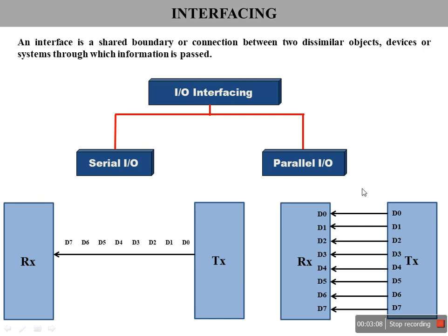Here, for example, if data is transmitted in a single clock, and assuming a single clock is 1 second, then the data transaction between these two devices will take 1 second to transmit 8-bit data, whereas the same 8-bit data with the same clock may take 8 seconds in serial. So with respect to speed, the parallel I/O interface is faster compared to the serial I/O interface,